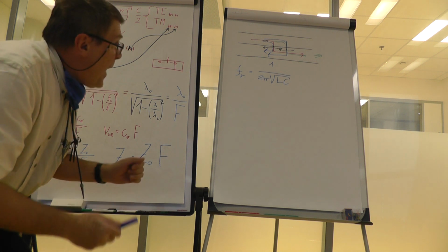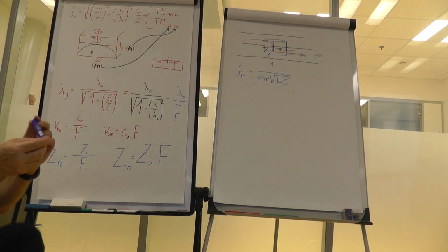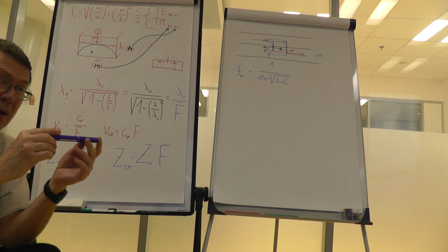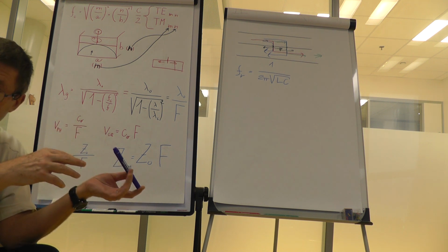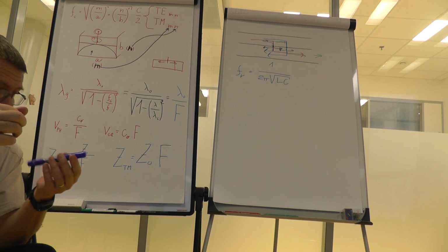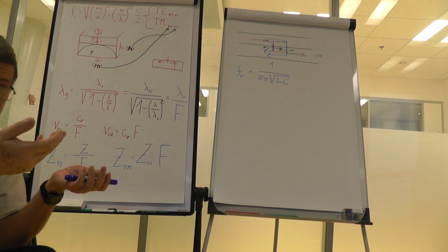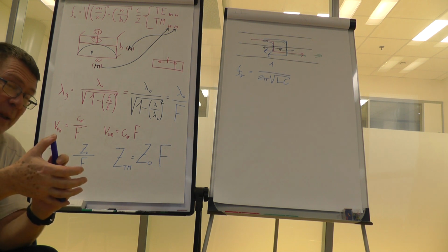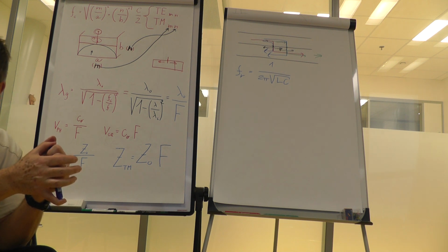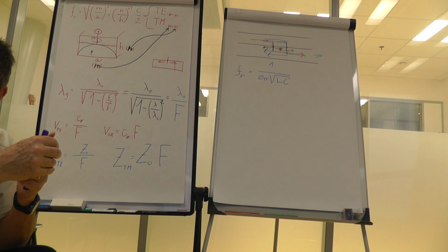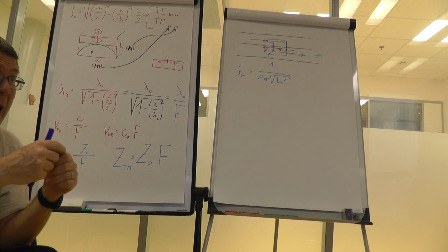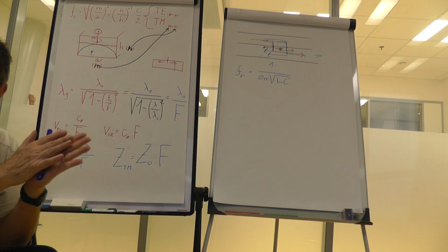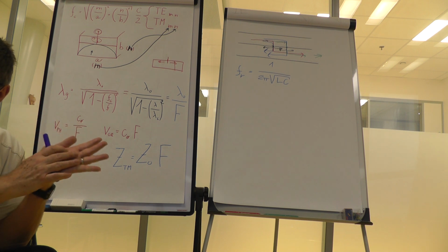And in fact, you get something for thin wires like those that connect silicon chips to the package, which is a golden wire, let's say 20 or 30 micrometers in diameter. This kind of wire has something like 1 nanohenry per millimeter.